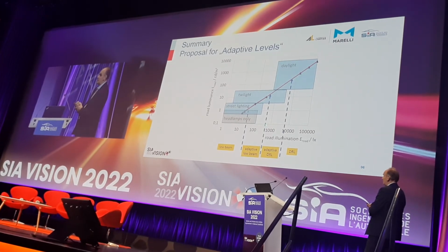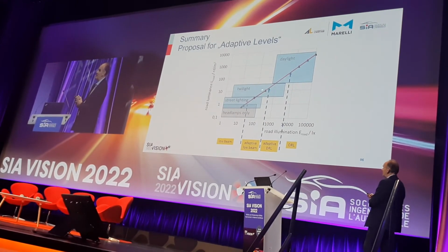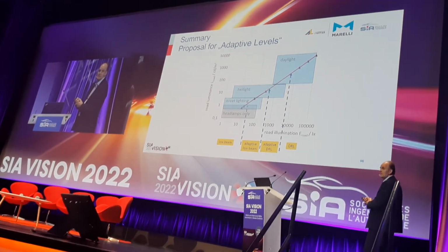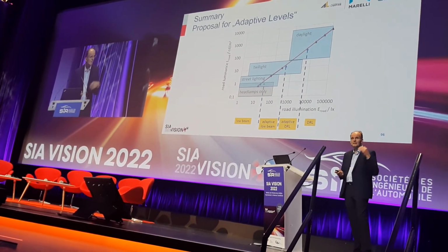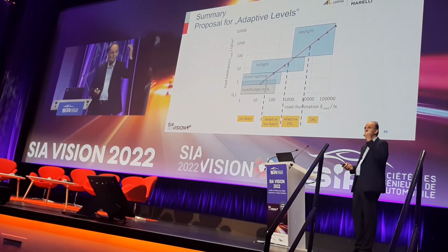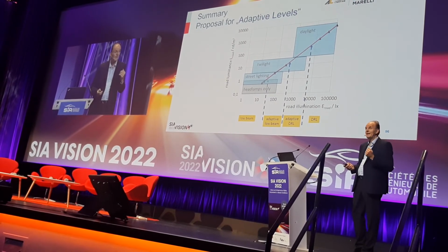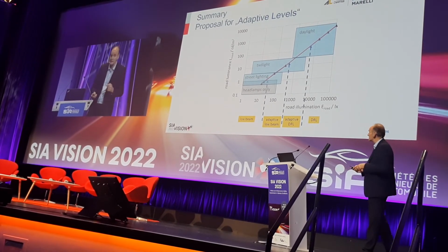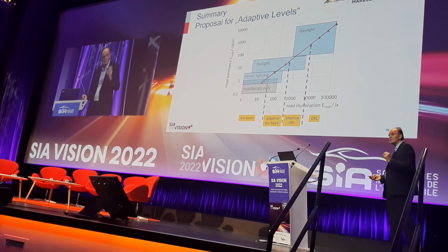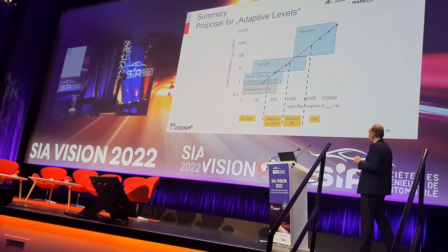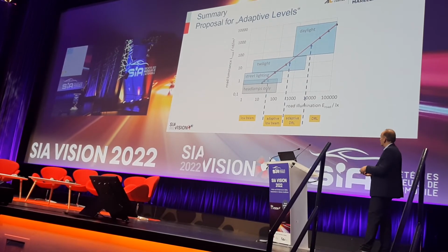At 500 lux on the road we are at 30 candela per square meter. The adaptation of the human eye is not fully photopic at 500 lux. Therefore it makes sense to dim down, because then we are more sensitive to the blue amount of the LED light and to the recognition of the DRL.